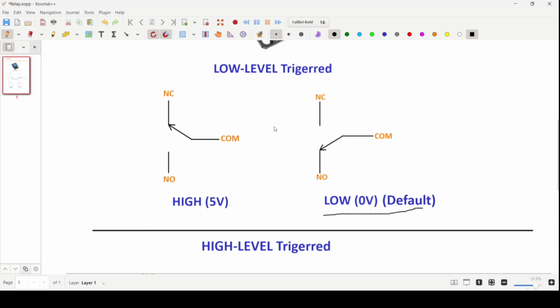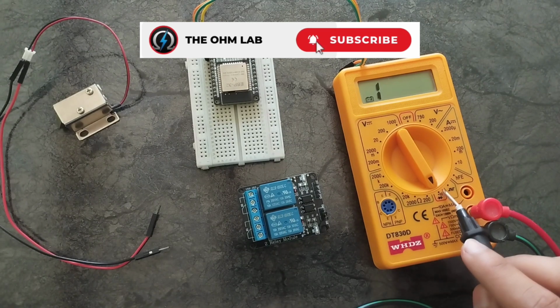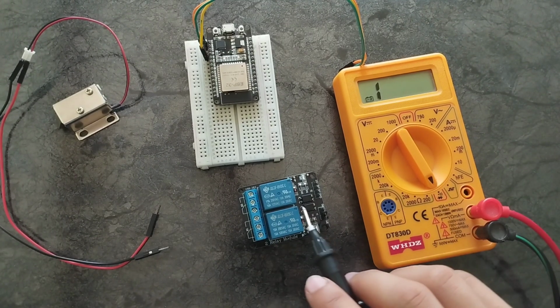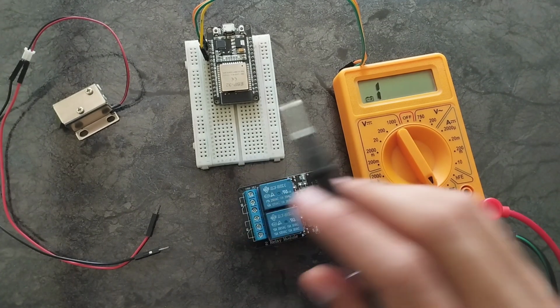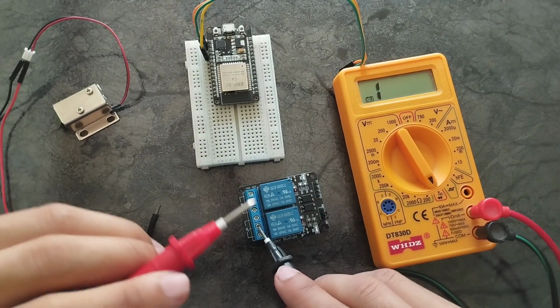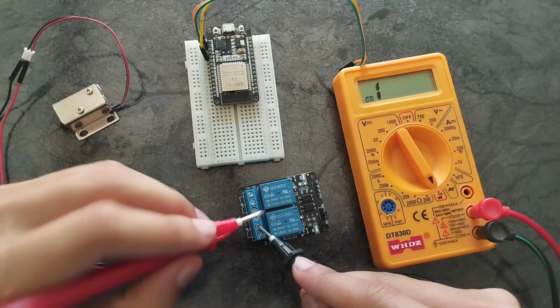Let me show you. In order to check whether my relay module is low level triggered or high level triggered, I am using the continuity mode of the multimeter. And you can notice one thing, I am not providing any power supply to the relay module from the ESP or any other battery. Okay. And I will touch one of the probes to the common pin, any probe, whether red or black, and the other probe to the normally closed pin and normally open pin one by one.